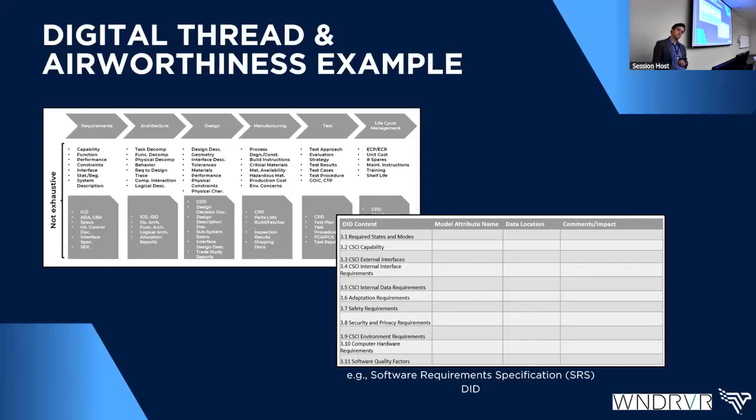And the thing we're finding is I can't impose the rigor that the regulatory or statutory airworthiness requirements ask of me on the requirements themselves, where I can have atomic-level source control of the requirement in the tool we have in Cameo. So on his side of the fence, they're saying, Tyler, Cameo is the source of truth. Everything's going to go in Cameo. On my side of the fence, all my vendors are using a tool dedicated to requirements management, because in Cameo I can't trust a checksum for a project when it gets committed, when it gets saved down. I can't go and reverse look at the history at an individual element ID. So that right there put me in non-compliance with my airworthiness objectives for requirements.